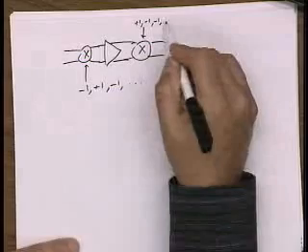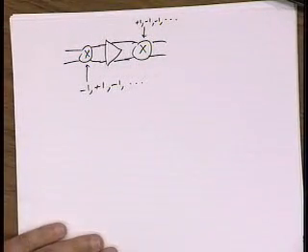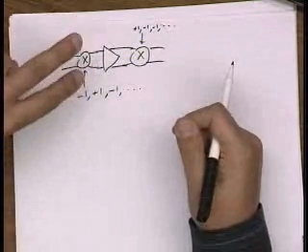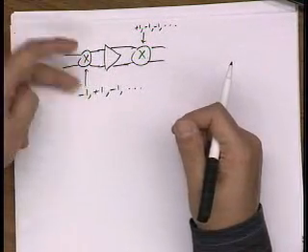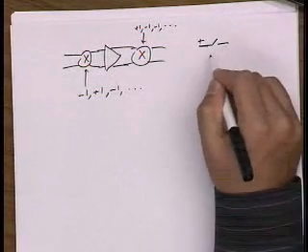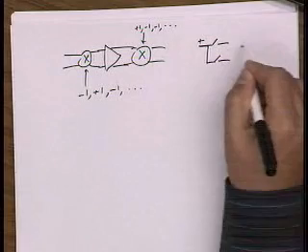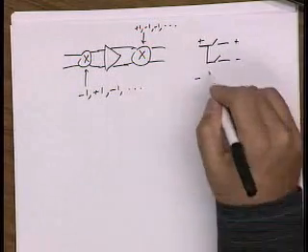So how could I achieve that in a very simple way? I could just flip my inputs, right? So one cycle I put my input positive, next cycle I put my input negative. So I just have switches. I take my positive input and I can either apply it to the positive terminal or the negative terminal, and the same thing for my negative signal.